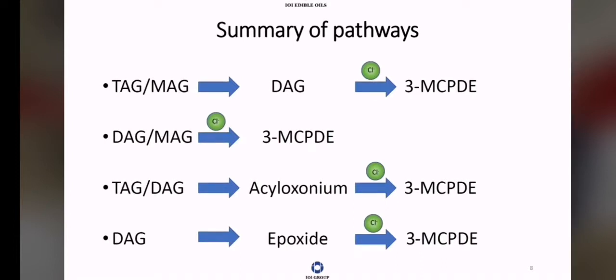Now, another approach, another thinking that has come about, is that in the palm oil there is a lot of inorganic chloride. And we have looked at how we can remove that inorganic chloride because it forms a substantial portion of the chloride presence in oil. And one of the good things about inorganic chlorides, if you remember your chemistry again, is that most of the chlorides are highly soluble in water. So just using water would be a very good way of removing the chlorides, which is again an approach taken by most of the refiners.